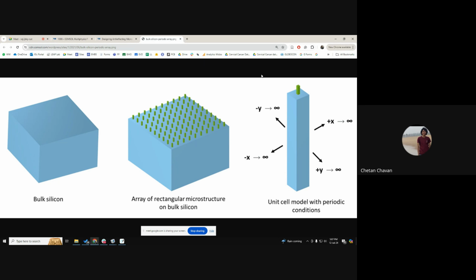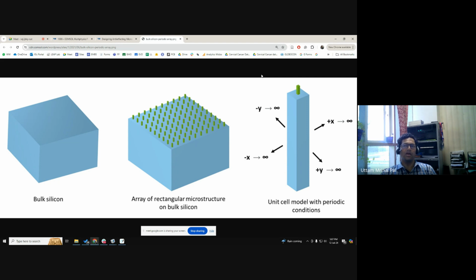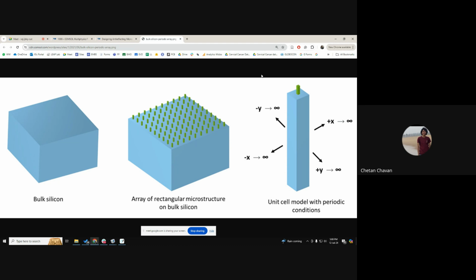But do we have this kind of arrangement getting repeated, or is it completely random? No, there is a specific formula that we need to feed in to have this arrangement. For example, when I know that the lens should meet a certain criteria, let's say this much focal length and this much diameter, f and d. Once you specify these two, ANSYS self calculates where to place the meta atom and with what geometric changes it has to place the meta atom.